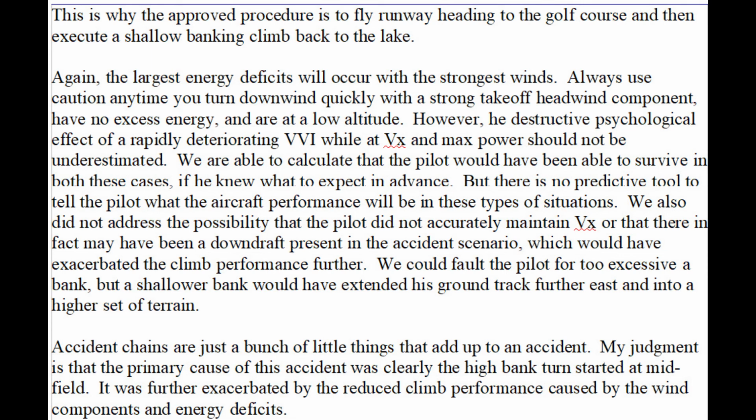Again, the largest energy deficits will occur with the strongest winds. Always use caution anytime you turn downwind quickly with a strong takeoff headwind component, have no excess energy, and are at a low altitude. However, the destructive psychological effect of a rapidly deteriorating VVI while at Vx and max power should not be underestimated. We were able to calculate that the pilot would have been able to survive in both these cases if he knew what to expect in advance, but there is no predictive tool to tell the pilot what the aircraft performance will be in these types of situations.